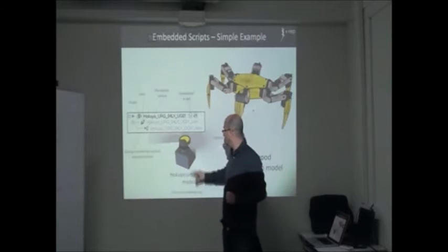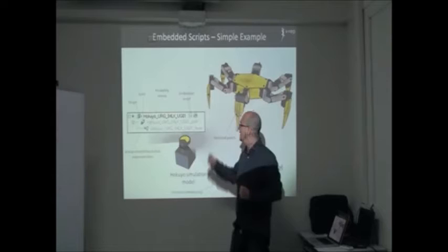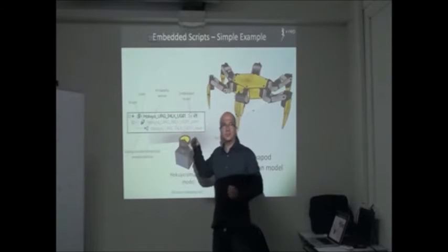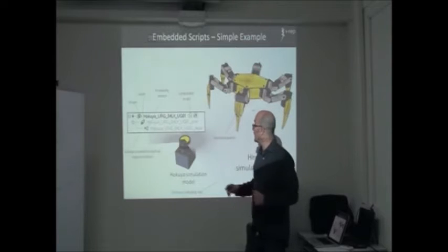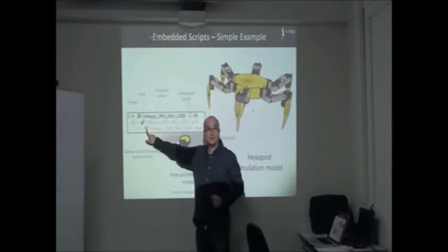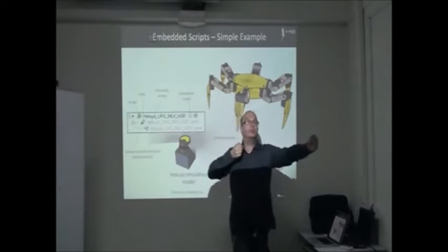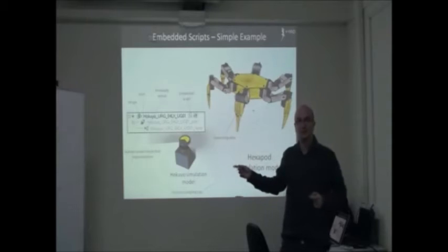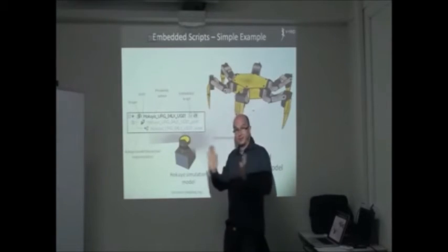So the point is that you have this sensor that exists in real life. You can buy it. It's a Hokuyo sensor. You can get the specification of the distance it can detect and in which angle it is able to detect distances. So I take this proximity sensor. I parameterize it to be a ray with the maximum detectable distance, which is written in the specification. You can write that down, reuse it, and parameterize it like that.